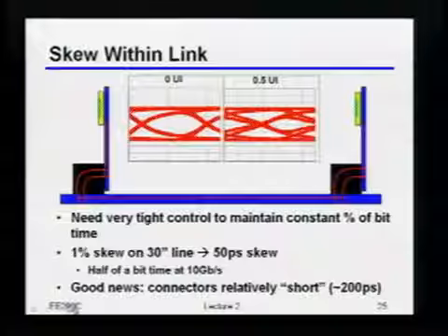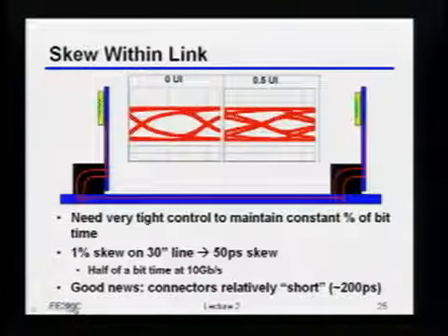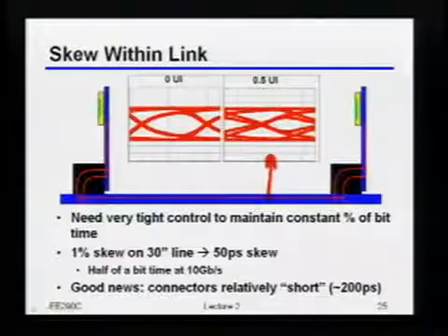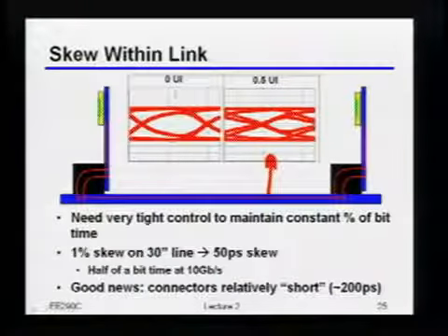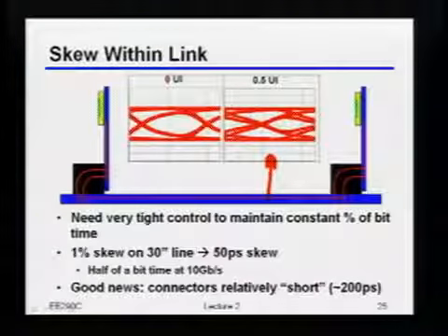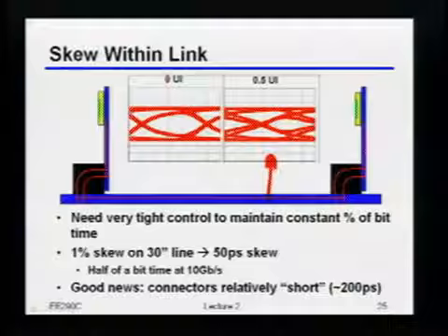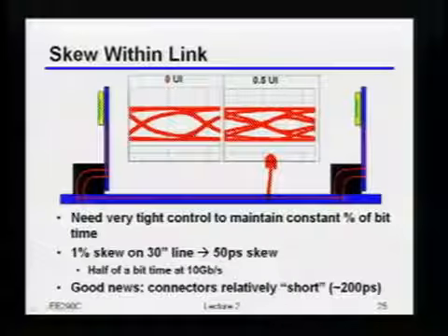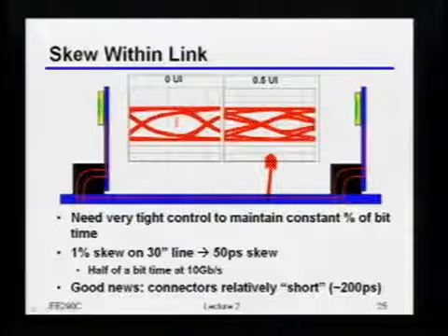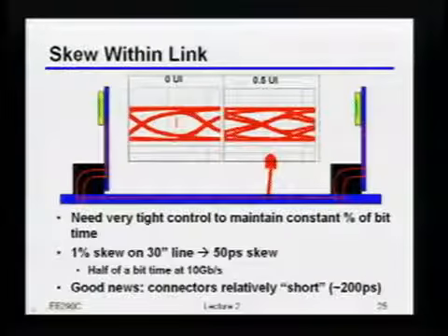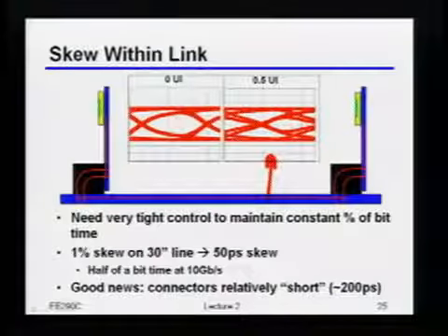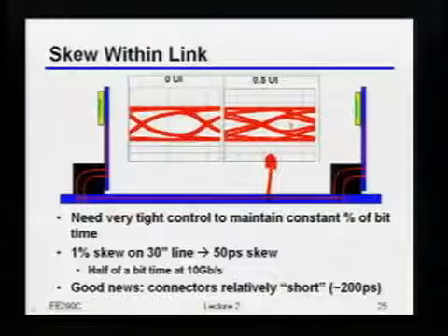Well, even just from the standpoint of the signal, if my plus and minus are misaligned, as you can kind of see in this picture here, my eye diagram gets completely messed up. Right? So here I have 0 UI, by the way, UI just means unit interval. That's like the bit time. If I have both my plus and my minus lined up perfectly with each other, nice clean eye like this. If I just take the plus and the minus and shift them by half a bit relative to each other, well, guess what? You're getting garbage for a large period of the time. It's basically, you've thrown away half of the time where you actually could have gotten a reasonable signal.